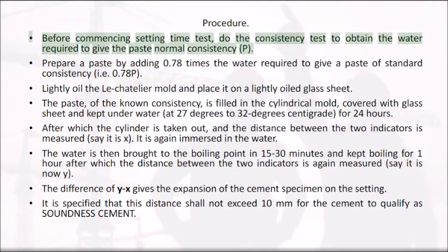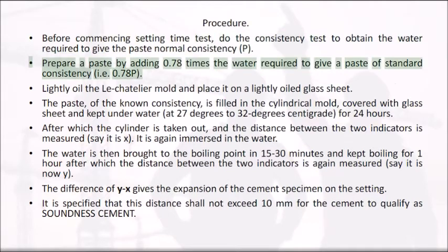Before commencing setting time test, do the consistency test to obtain the water required to give the paste normal consistency, P. Prepare a paste by adding 0.78 times the water required to give a paste of standard consistency, i.e. 0.78 P. Lightly oil the Le Chatelier mold and place it on a lightly oiled glass sheet.